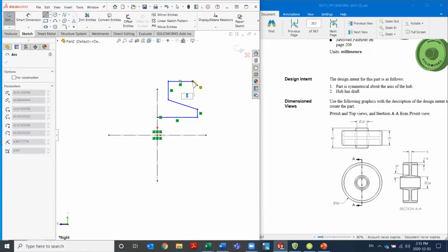And this actually will produce a number of arcs for you. So depending on where you drag your cursor, so I dragged it straight out here, and I can go up and down here. Or I can go back this way and create arcs this way, and even go from the top or the bottom. So I can create a number of different arcs really quickly and easily with this.